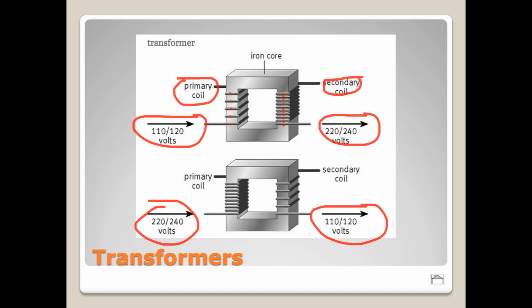So if you had a buck boost transformer like this, let's say maybe you're setting up a piece of equipment that you normally use here in the States that does not have an auto sensing power supply, and you need to run it on a tour in Europe. Then you can simply plug this in. It will take this 220 or 240 volts, and it will step it down to something that your American piece of equipment can run off of. Or vice versa.